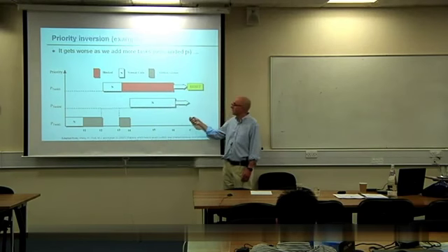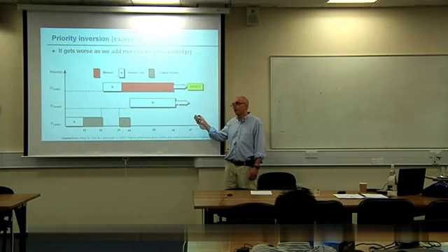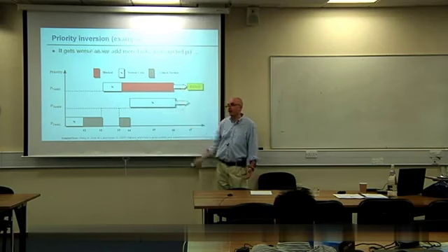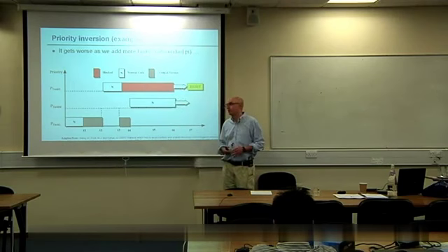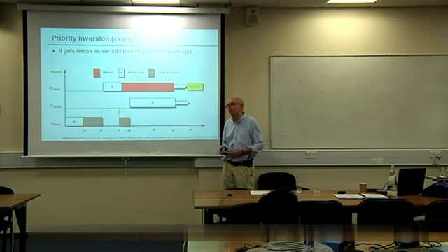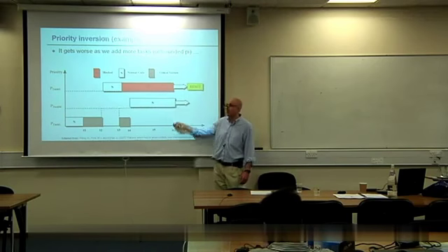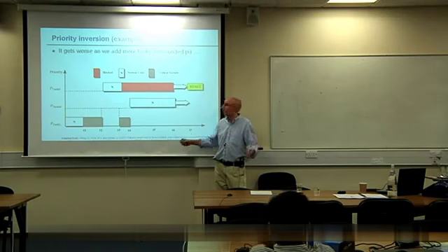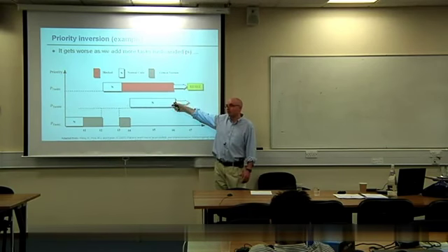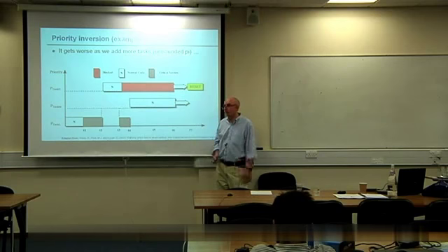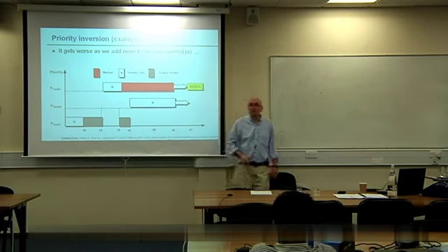Because this is unbounded. This could be any duration at all. Typically, OSs might have a couple of hundred possible levels of tasks. They won't have a couple of hundred tasks running, probably maybe 50 tasks in a typical system. Suppose you have half a dozen tasks of different durations, potentially with their own sets of critical sections that they're fighting over, and they can interrupt this kind of behavior. In any practical sense, it's impossible to predict this behavior.